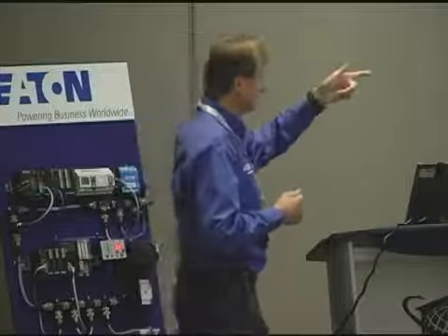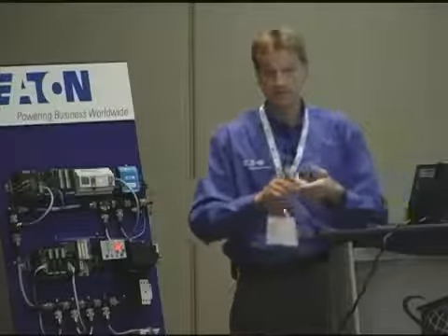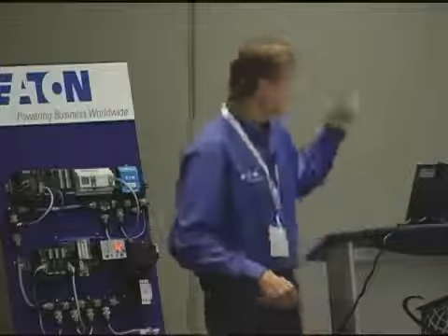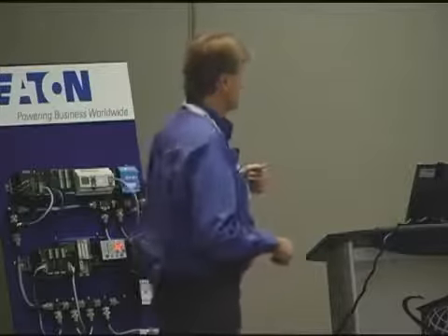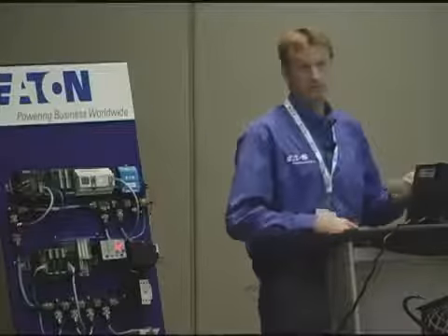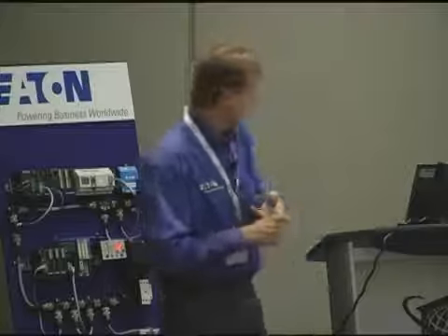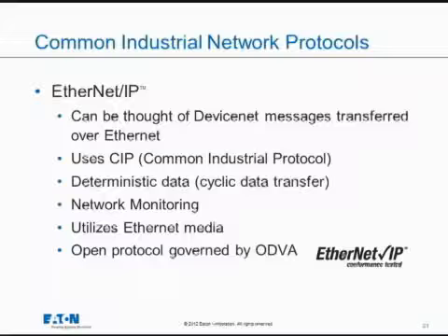It has deterministic data, as well as DeviceNet did. Sorry, I didn't put it on the last slide. So it does use scheduled messaging. It has cyclic data transfer. Again, it has network monitoring. It uses the Ethernet media, so now we can expand our network through routers and switches. We can have multiple levels. And it, again, is governed by ODVA, and there is a conformance-tested logo there on the bottom.